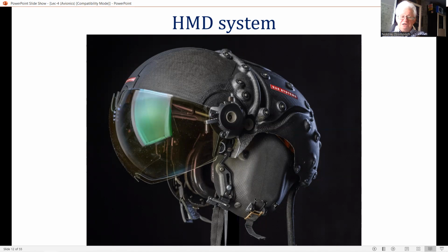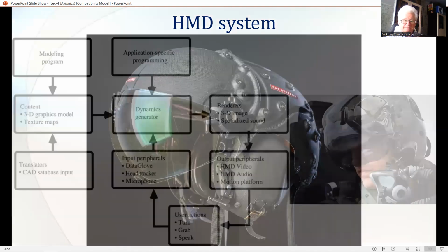Critically, the need to minimize the head-borne weight results in the CRT drive circuit being located remotely from the helmet, at the end of an umbilical cable. Such a widely dispersed architecture cannot achieve as high an integrity as a single unit HUD system.